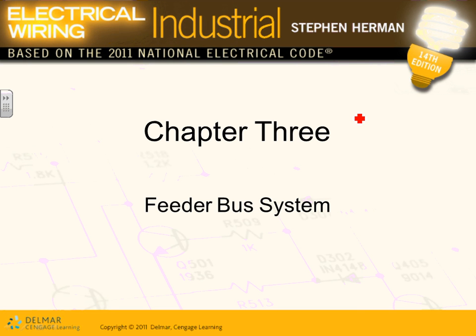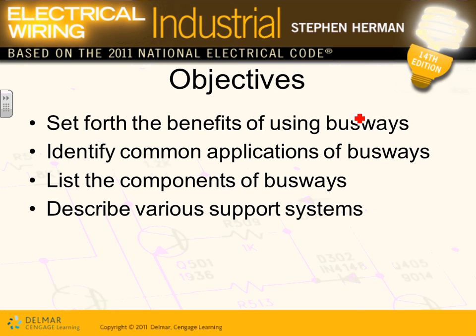So today we're going to talk a little bit about the busway. I already gave you guys two calculations for how to calculate the size of busways. The standard sizes for the busway are in the book. What I'm hoping we can do is cover the benefits of busways. Why should I go for a busway versus a panel? Every time you hear of a busway, think of a panel. A busway is actually an extension of a panel, because like panels, you can plug things into it.